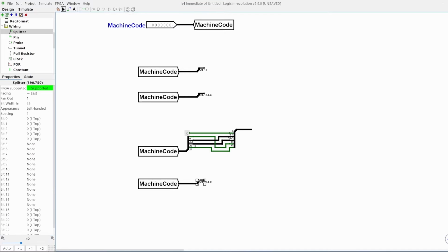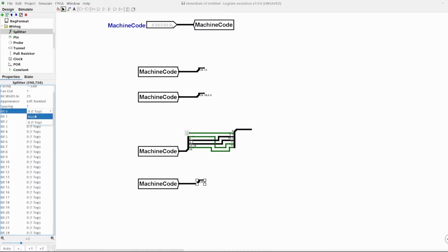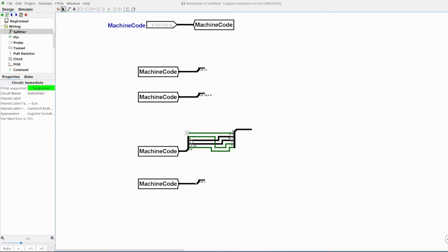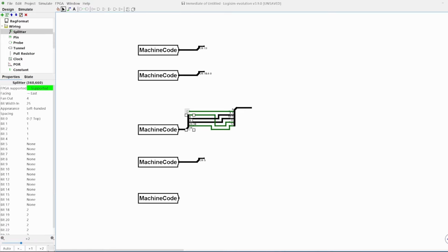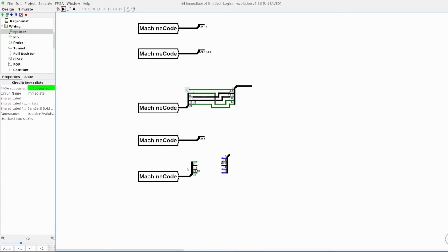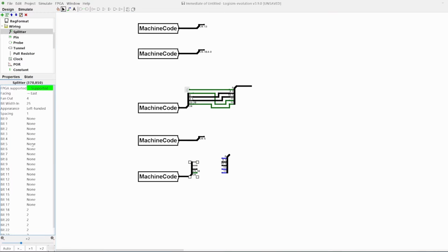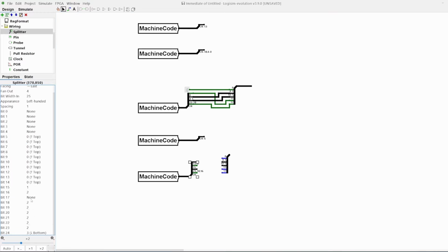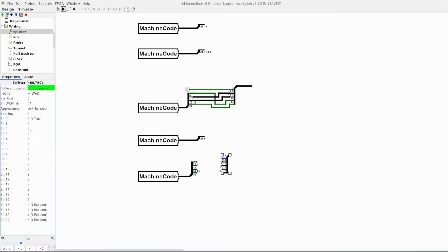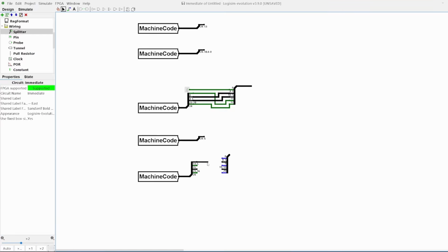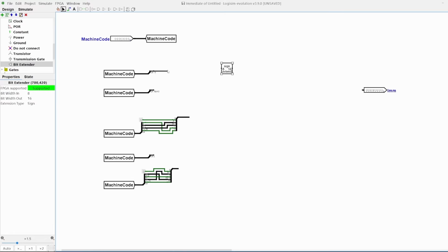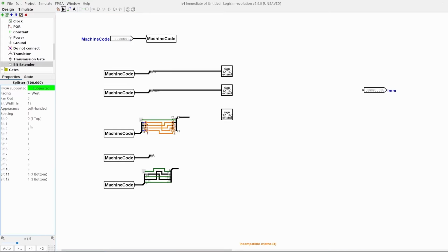U-types are just the last 20 bits, and for J-type instructions, we have to do the same thing as for B-type instructions, but now in a different order. Specifically, we ignore the first 5 bits, then combine the next 8, 1, 10 and 1 bits. Recombine them together with a constant 0, and we get our J-type. Let's sign extend all of these to 32 bits and add some labels to make it clear what each signal corresponds to.